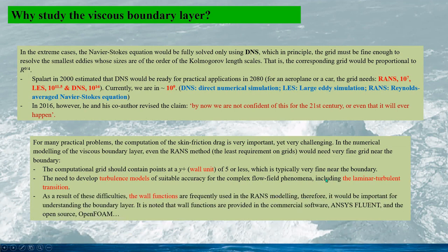In reality, the modeling of the near-wall flow often makes use of wall functions, such as in commercial software and in open source. This avoids resolving the boundary layer directly. In this regard, the understanding of the boundary layer would be very important.